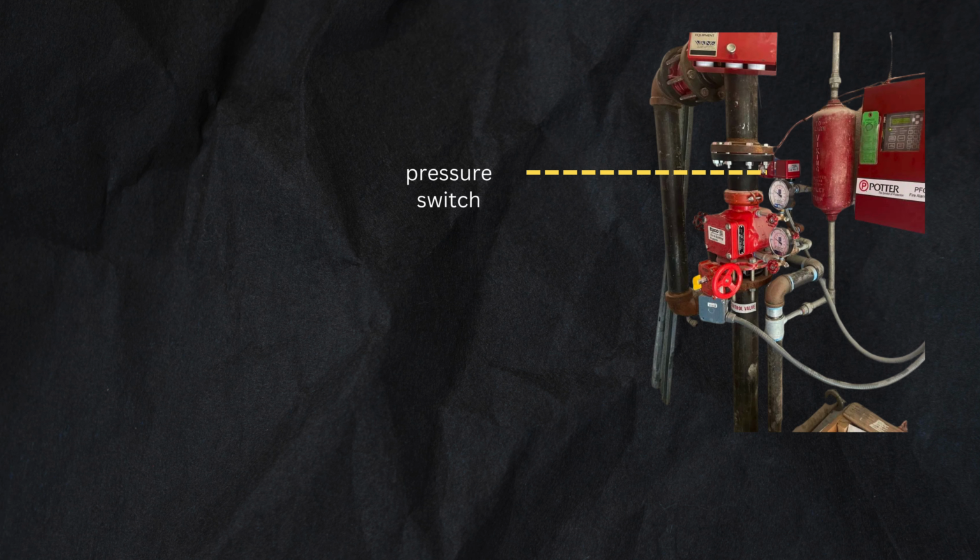Series pressure-actuated switches are designed for the detection of a water flow condition in automatic fire sprinkler systems of particular designs, such as wet pipe systems with alarm check valves, dry pipe, pre-action, or deluge valves. The PS10 is also suitable to provide a low-pressure supervisory signal, adjustable between 4 and 15 psi.